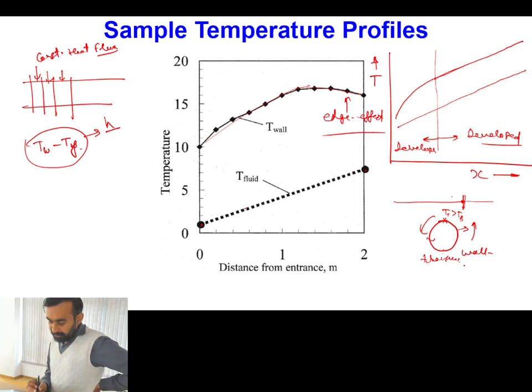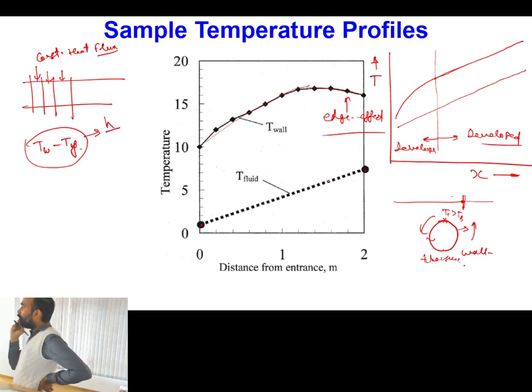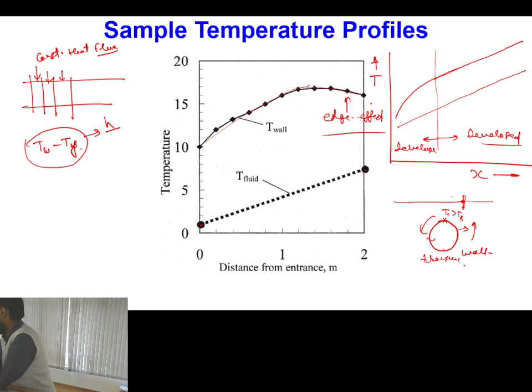And of course, putting a large number of thermocouples within the tube to measure the fluid temperature is not possible because of two reasons. One reason is, if you have a heated portion and you have to insert a thermocouple through the heated portion, there will be high chances of leakages or other issues, and the thermocouple may give a wrong reading as well because it has to pass through the heater coil.